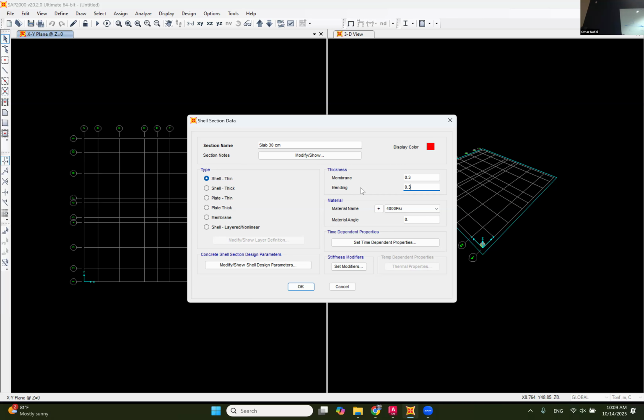Sometimes, as I told you, you have a wall, and the wall is usually designed to take loads in the strong direction. What is the strong direction of this wall? That way, right? This wall is weak in that direction. You give it load that way, it's going to bend that way. But it's stiff in that way.